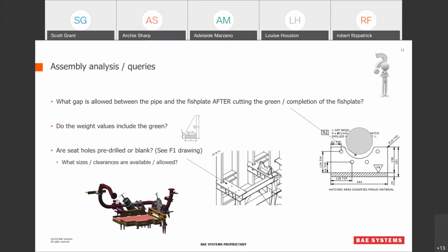But as you say, in certain drawings, the fish plate drawings in particular, it's maybe not clear whether the holes in the matching base plate of the fish plate are already drilled, and then you put the fish plate onto the seat and drill through them holes as a pilot hole, or is it a case there are no holes in either, or are the holes in the assembly on the seat there, and we have to drill the corresponding fish plate to them holes?